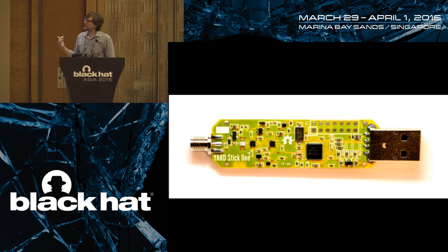And it implements certain modulations. It implements amplitude shift keying and frequency shift keying, which is like digital FM, and digital AM. It implements on-off keying, which is just turning on and off the radio, basically a crude AM. And it has a very flexible packet format.